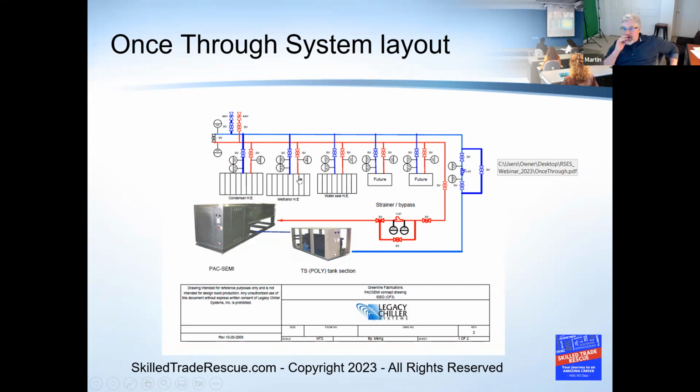If you have a chiller that's perplexing you and you're new on the site, first time you've seen it, and you can tell that this thing's plumbed as a once through, and intermittently it's tripping out on high head pressure, coils are clean, you did all your stuff, your glycol mix is good, your fans are all blowing air, the coils maybe a little dirty but not too bad, but intermittently it's just tripping out.